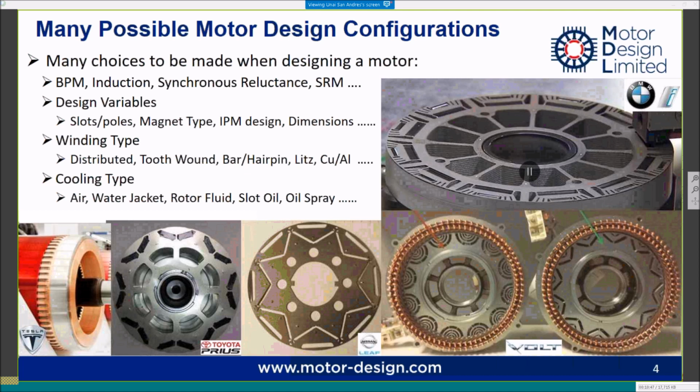After choosing the topology, which could be, for example, brushless permanent magnet machines, inner or outer rotor, induction machines, synchronous reluctance or switched reluctance machines, we need to define the dimensions of the different parts of the machine, like magnets, the lamination, the winding, and everything is parameterized from the interface. So it can be done in a few minutes. The models can be generated for both the electromagnetic and the thermal models.